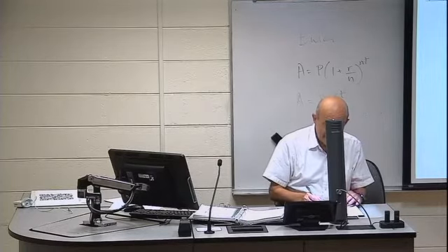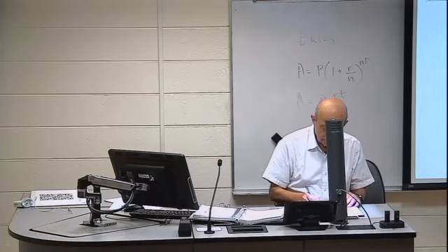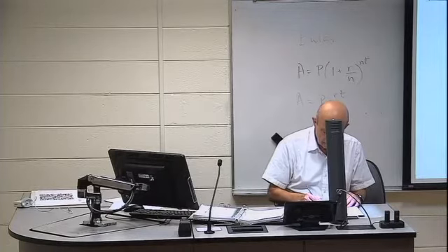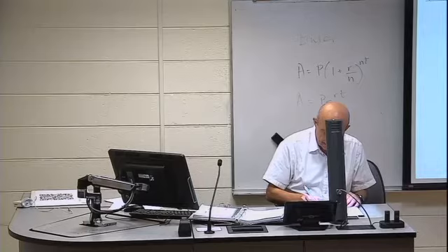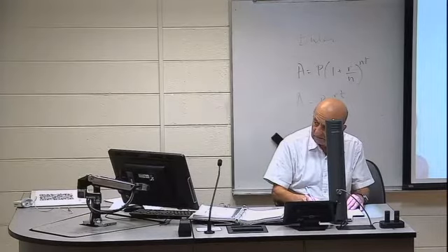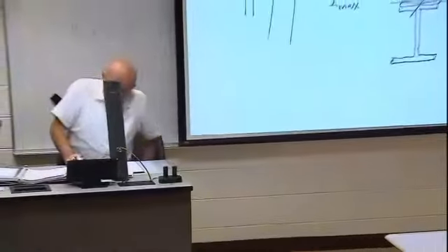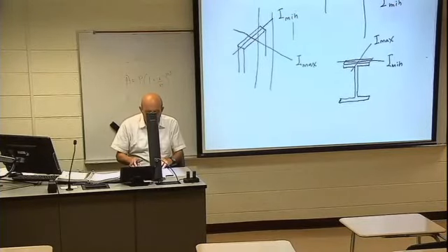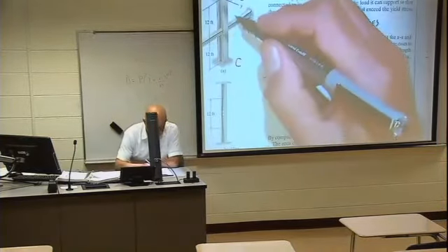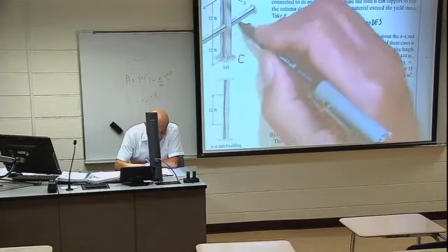Likewise, when we have an I beam, there is this I max, that is here, and that is I min. So if we don't do the bracing, then there will be buckling in the YY direction, so we are doing this brace.